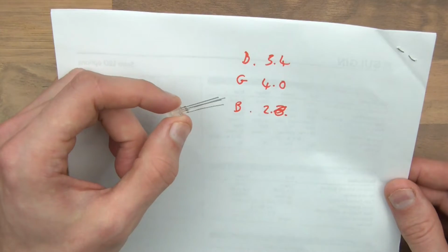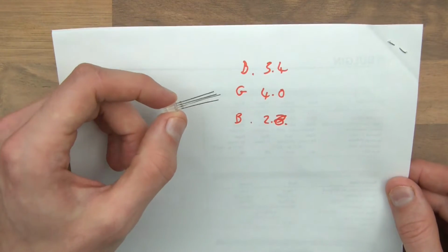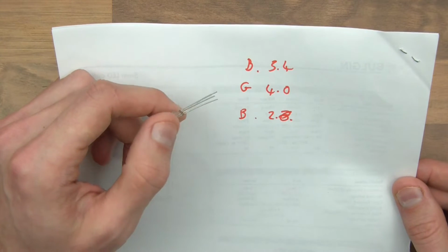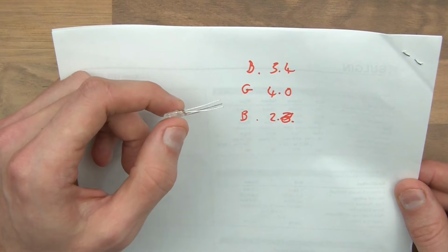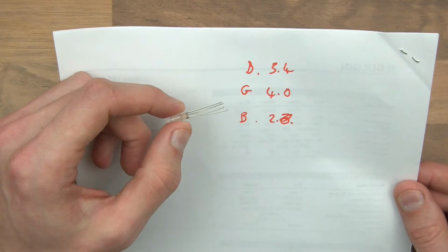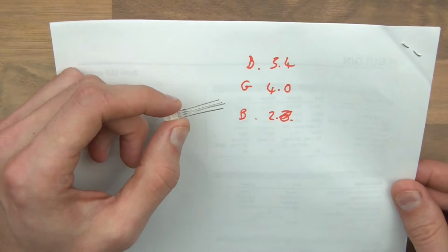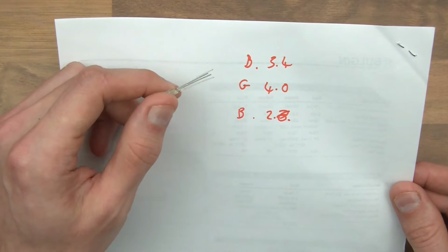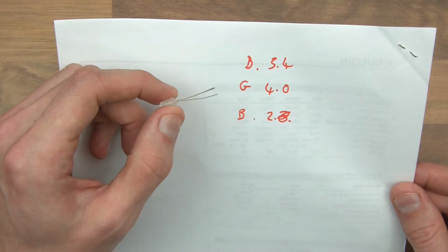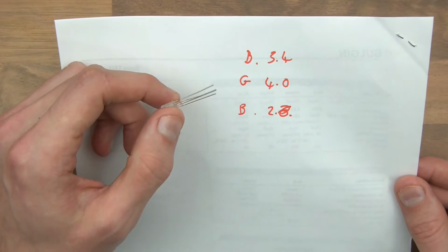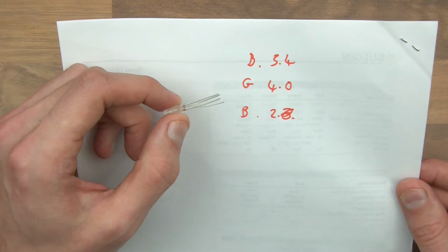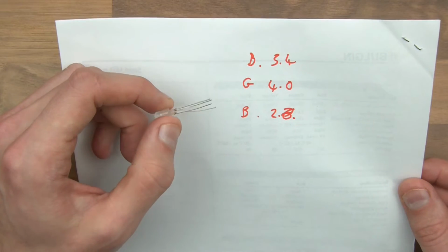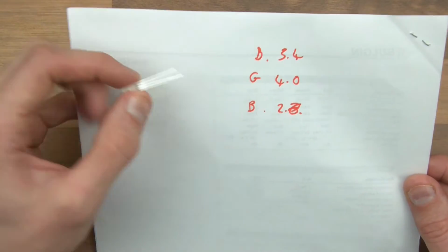So now if I've got the forward voltages, and let's say we've got a 6 volt power supply, then how can I stop this thing from burning itself out? Well, the answer is to use a current limiting resistor, like I just mentioned a minute ago, and I'm going to explain to you, hopefully simply, how you can just work this out for yourself, because a lot of people use online calculators and they don't really understand, but it's actually not that difficult. All you need really is a knowledge of Ohm's law, and the rest of it you can work out yourself. So I'm going to try and explain this to you now, and hopefully you'll like it. Okay.